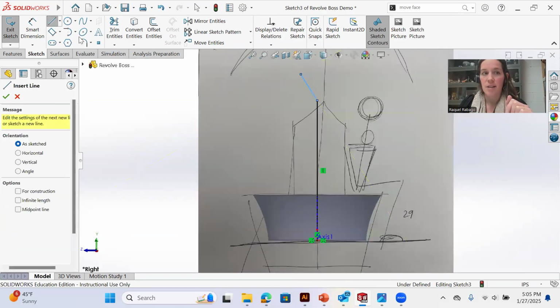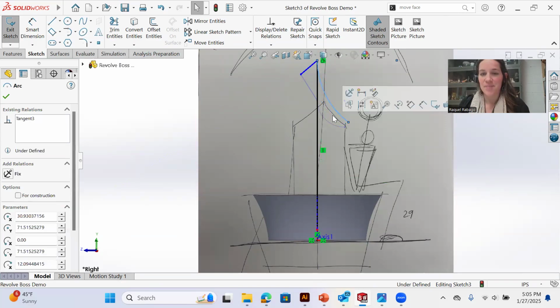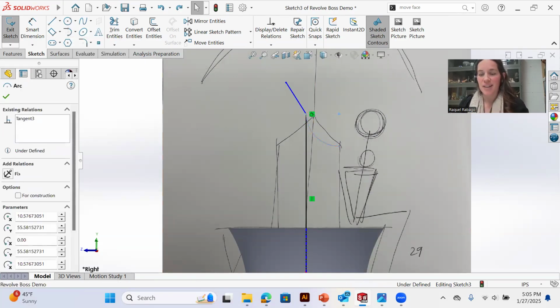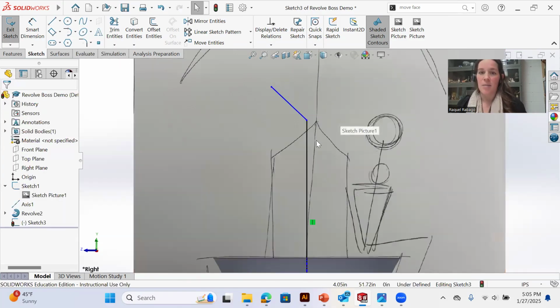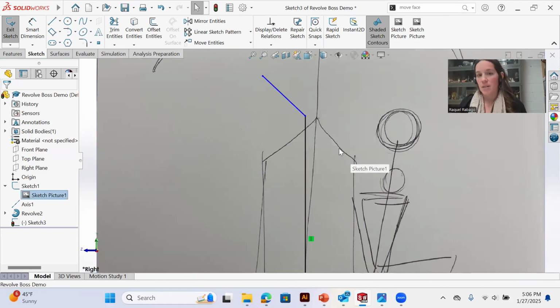You can see my sketch is approximating what I have here. Not very well. And I first selected the tangent arc feature, but it seems like that's going to be a little fussy. So when you talk about tangency, what you want to understand, if you haven't used this widely in Rhino before, is how you can plan what it's going to look like and how to define a tangency based on some extra geometry. So right here, look at this slope.